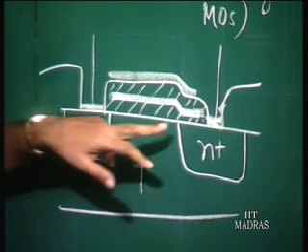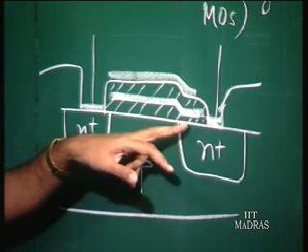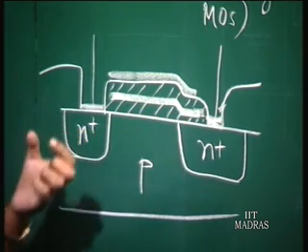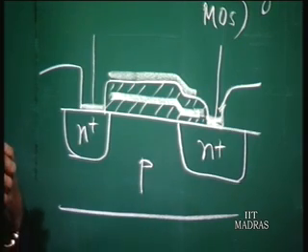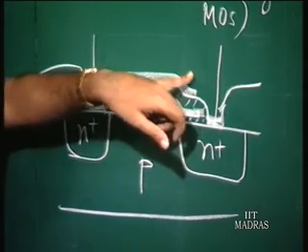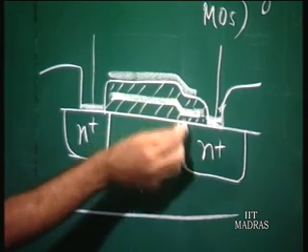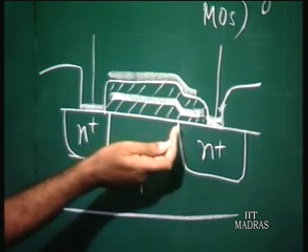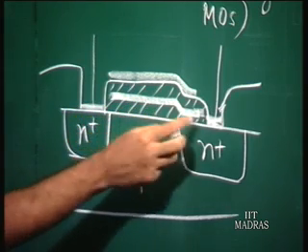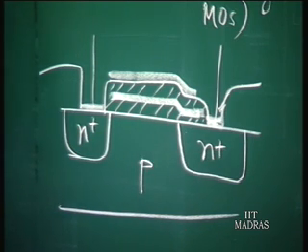So basically the difference here is that over the drain you have the floating gate, and here the oxide thickness is very small, much less than 100 angstroms. If you apply a large positive voltage on the control gate with respect to the drain, the electrons will tunnel through the oxide and get implanted into the floating gate. And because this oxide is very thin, it's a tunneling oxide basically, this process is going to be quite fast.